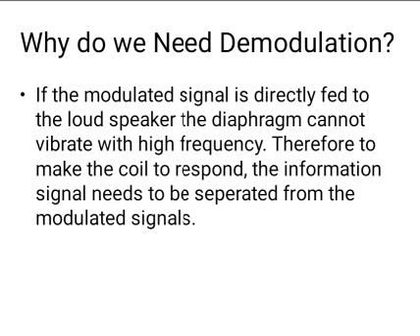Why do we need demodulation? If the modulated signal is directly fed to the loudspeaker, the diaphragm cannot vibrate with high frequency, that means radio frequency signal. Therefore, to make the coil respond, the information signal needs to be separated from the modulated signal.